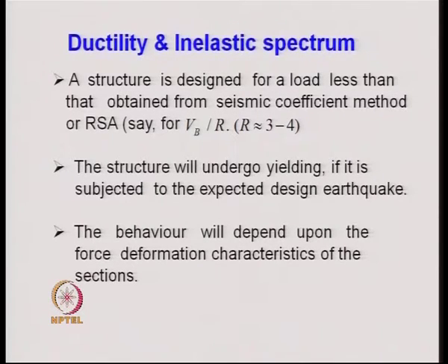The structure will undergo yielding if it is subjected to the expected design earthquake, that is what I told you before. The behavior will depend upon the force deformation characteristics of the section. So, that is again one of the important inputs for the analysis.